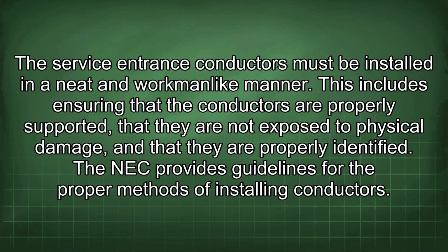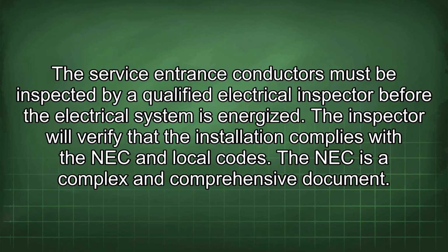The service entrance conductors must be installed in a neat and workmanlike manner. This includes ensuring that the conductors are properly supported, that they are not exposed to physical damage, and that they are properly identified. The NEC provides guidelines for the proper methods of installing conductors. The service entrance conductors must be inspected by a qualified electrical inspector before the electrical system is energized. The inspector will verify that the installation complies with the NEC and local codes.